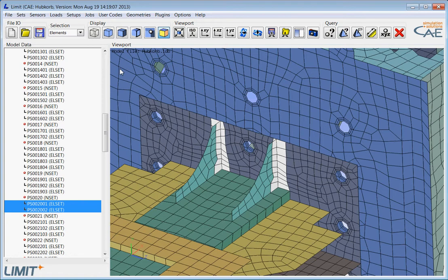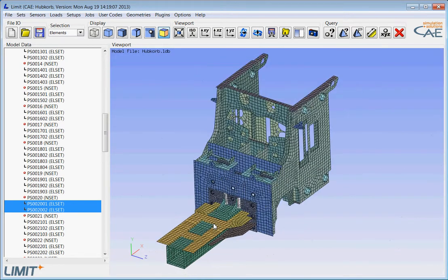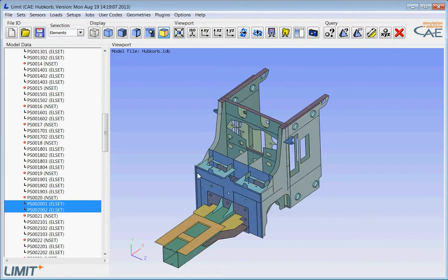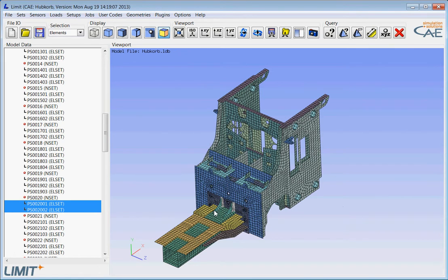Okay, so we have defined node sets. We have one overall set which we can use for the global weld assessment, and after that we can take a close look at the locally highest loaded weld, and in this case we can use these local weld sets.